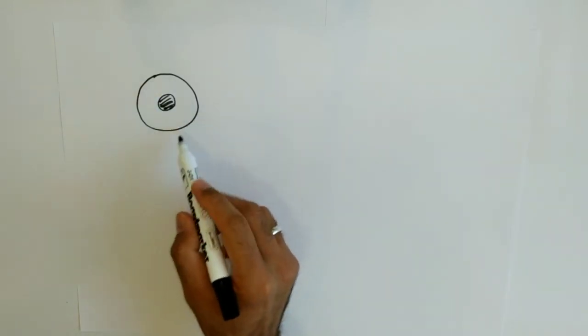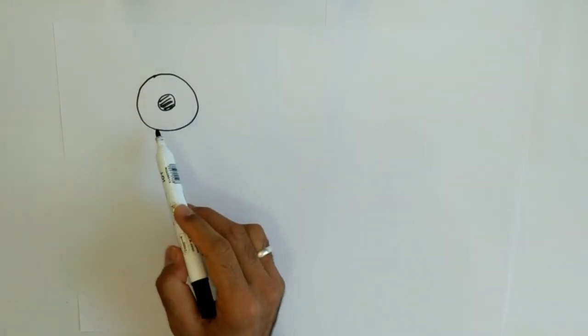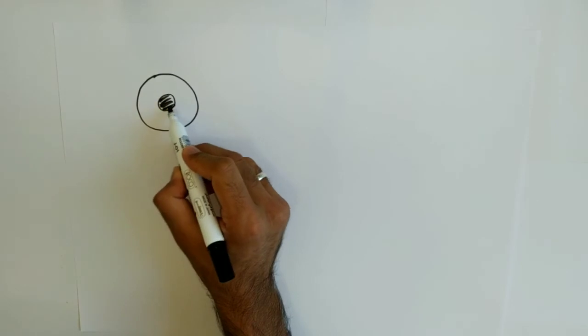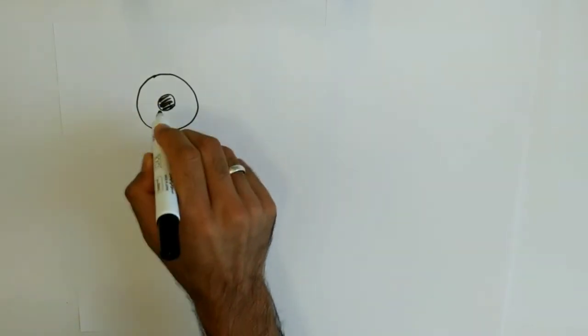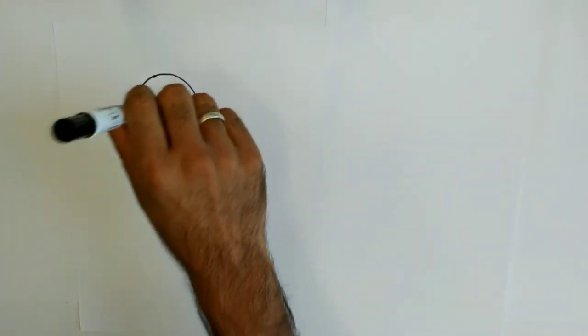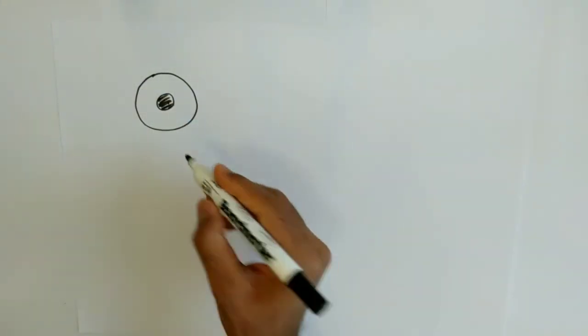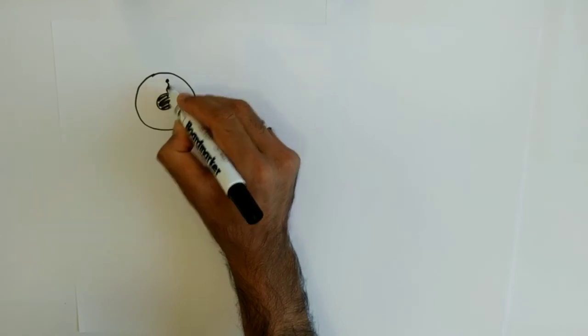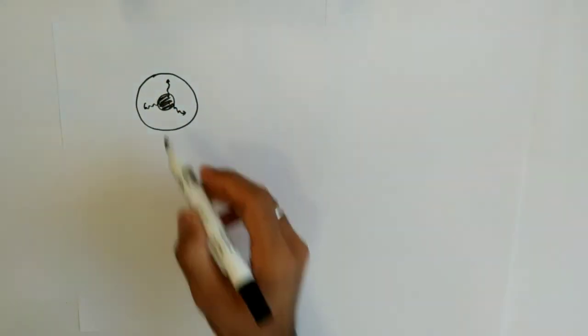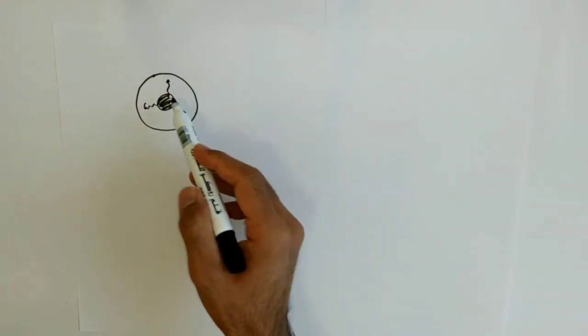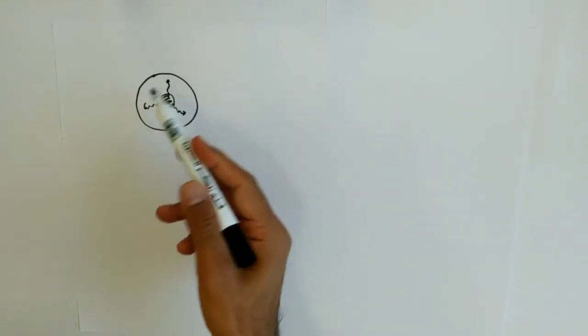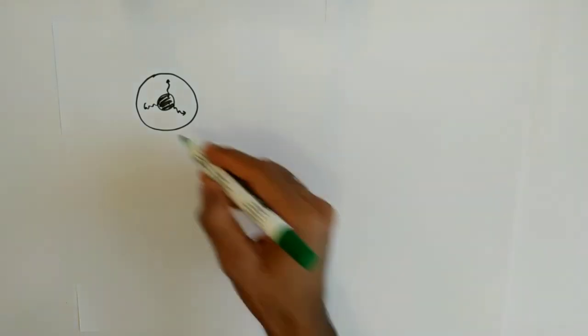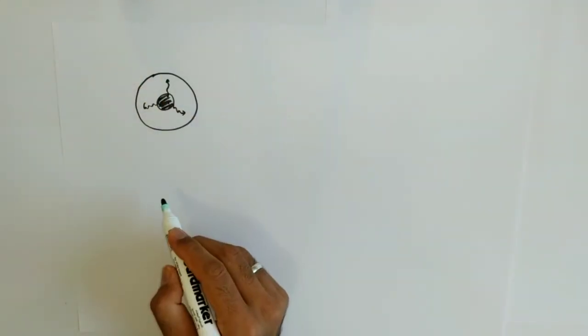Let us do the calculation or the derivation for the cable. In this case, this is your conductor which is carrying the current. The current is normally flowing in the conductor, but there are some chances that the current leaks out. This is what we try to check when we do the Megger test, the IR test or the HV test. In the HV test we check the milliamps; for the Megger, we generally check the milliamps, then it calculates the insulation resistance. As the current leaks through this cable, it is going in a radial direction.